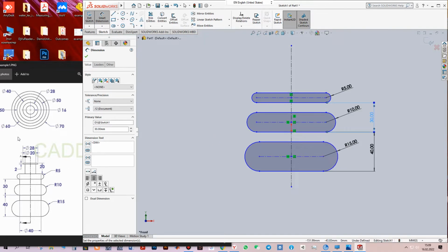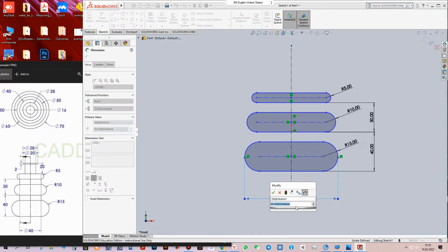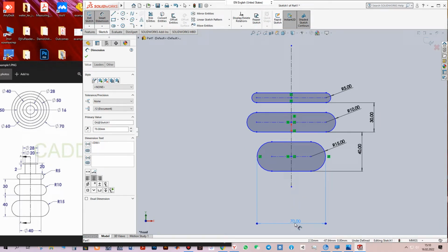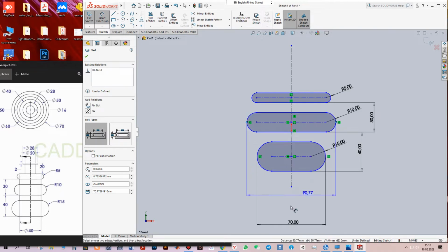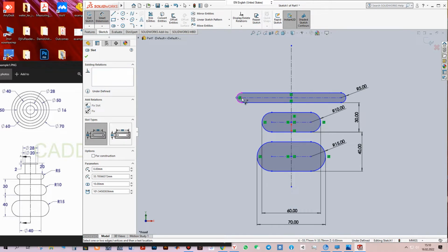What we can do next with the dimension is to configure diameters of that object. The bottom one equal to 70, this one, second one 60, third one 50. So how to set the dimension? We can move our mouse to this curve, then this yellow object will be highlighted. We click on this one, then we wait till it will be highlighted here, click this one. So this one equal to 70. Second one should be equal to 60. And the last one should be equal to 50.